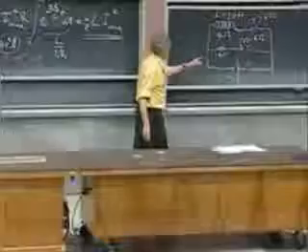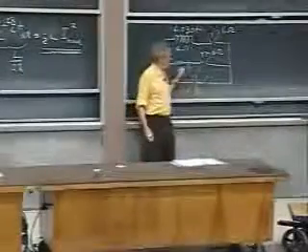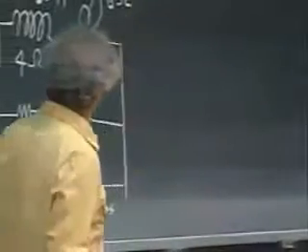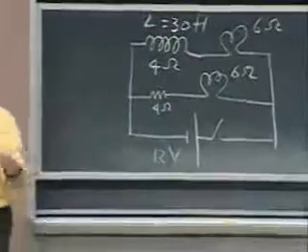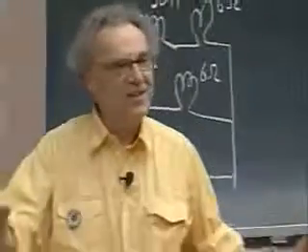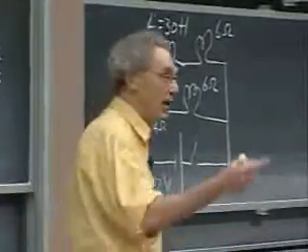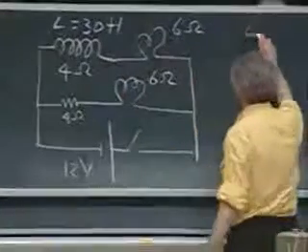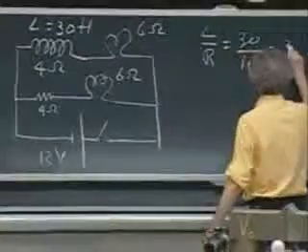And I'm going to throw the switch, turn it on. You will see that this light bulb comes on almost instantaneously. There is no self-inductance in this loop. Well, maybe a few microhenry or even less. But in this loop here, there is this huge self-inductance. And so the self-inductance says, take it easy to the current, take it easy, just wait, and you will very slowly see that light bulb come on. And we can calculate how long it takes. Because we have here 10 ohms, 6 ohms, and 4 ohms. So L divided by R is 30 divided by 10. So that is 3 seconds.